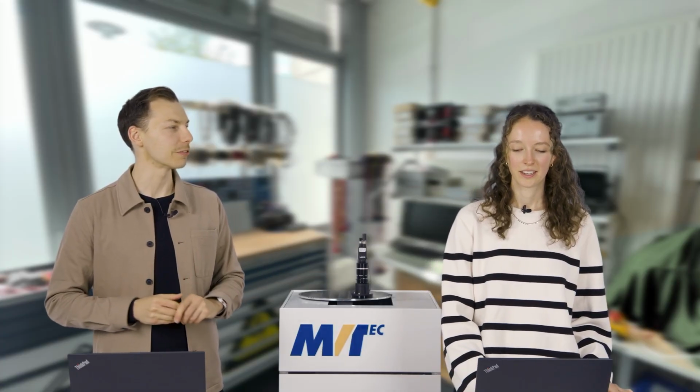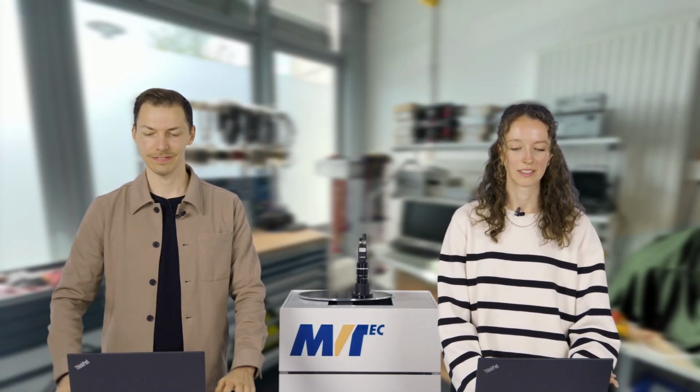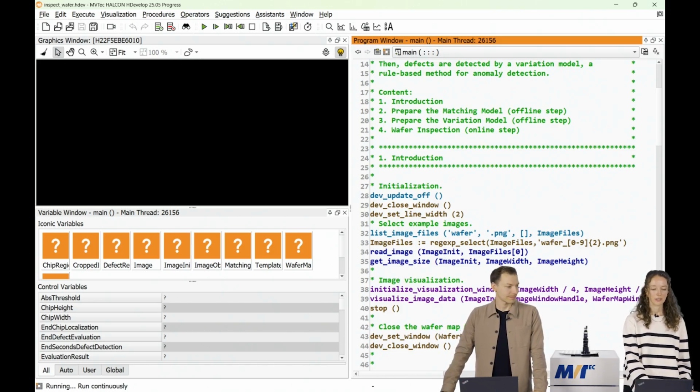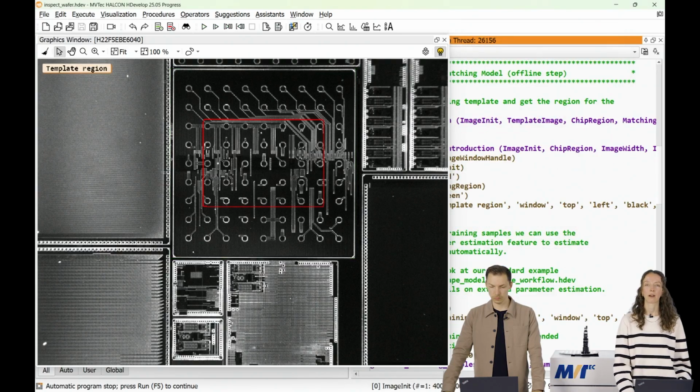Okay, I think with that, if you like, you could guide us a little bit through the single steps of the vision algorithm. Yes, of course. Cool. So I prepared a script, and in the first step, we see just the image that we acquired, which you also saw in the live demo before. And now we have to define a matching region. The matching region doesn't have to be the whole chip. It just needs enough descriptive structures. So it's also enough to just take the inner part of the chip, as you can see here.